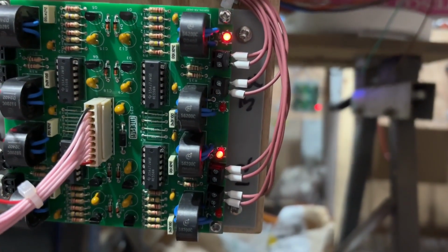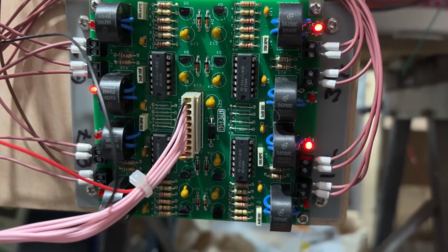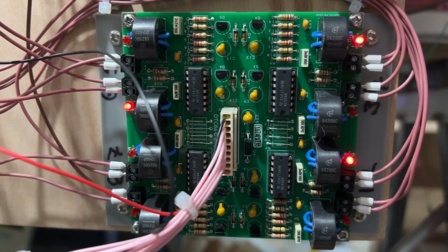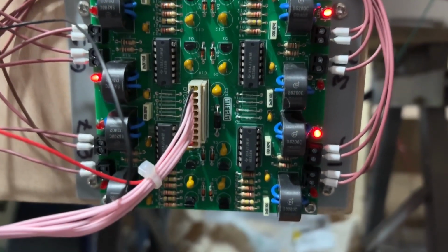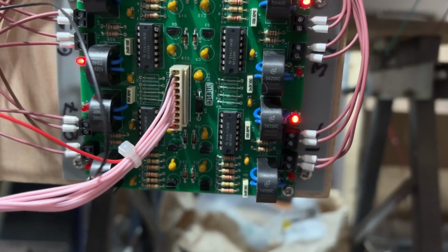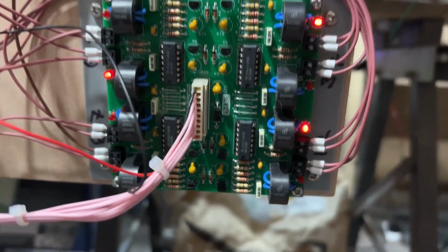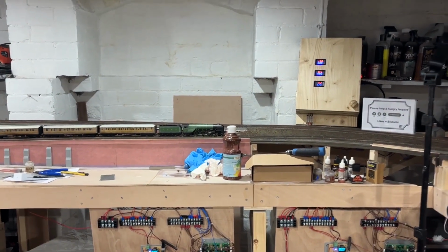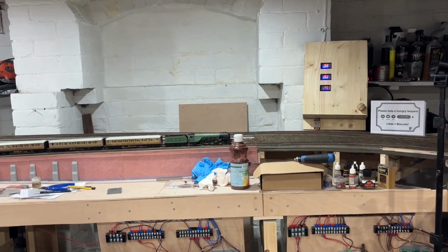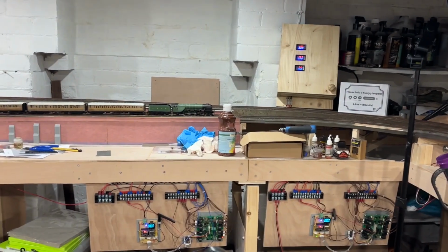Well, whenever one of these red lights is on, it's being reset constantly. So the output stays on. And then when the train disappears, it takes about a second for it to say, hang on, there's no train here. But what that means is if you lose contact for half a second, 1/10 of a second, whatever, this detector doesn't notice. It just says there was something here about a second ago. Yeah, it's probably still here. We'll wait. And then the train will come back. And that's really useful. It debounces the circuit. It smooths it out. It's a lovely little circuit. It's a really nice idea.